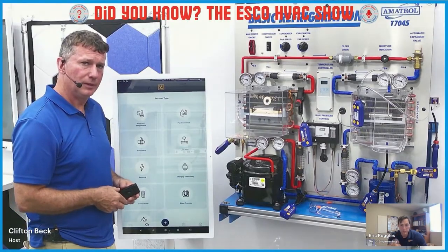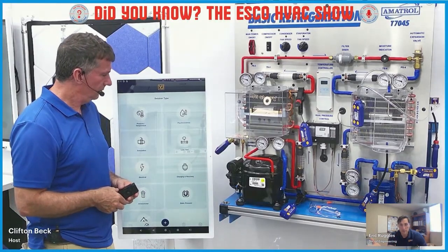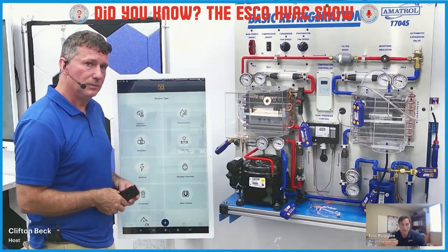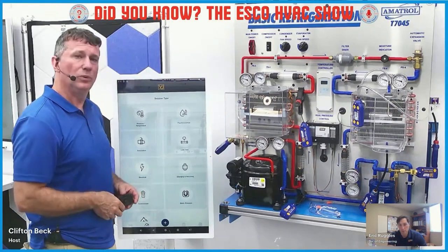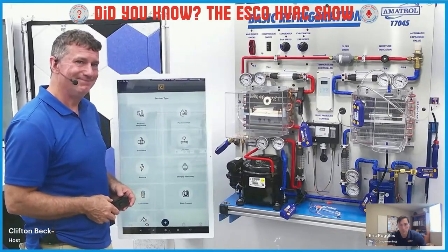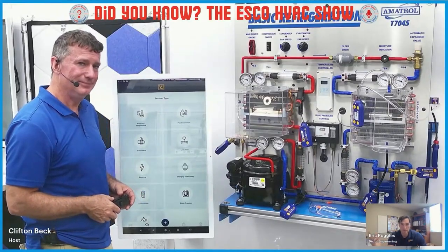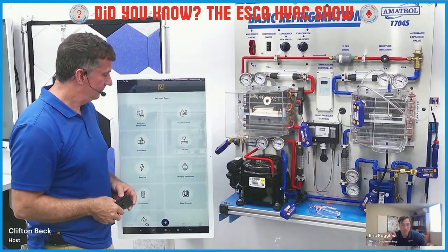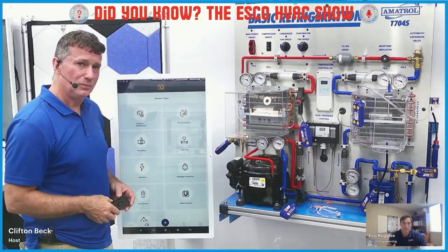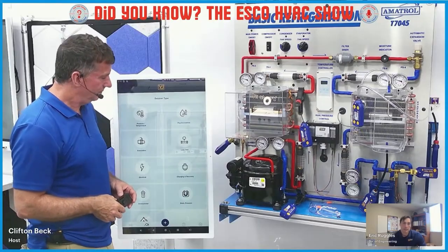Same thing for the leak test. That would typically be a nitrogen pressurized leak test. And then you can either use temperature compensation or not. So if you have a pressure sensor and a temperature sensor, you can use both of those to connect up to the system, and it'll do the full test for you as well, picking what your acceptance level is of a leak or pressure change.